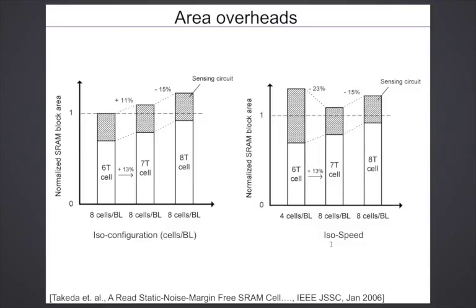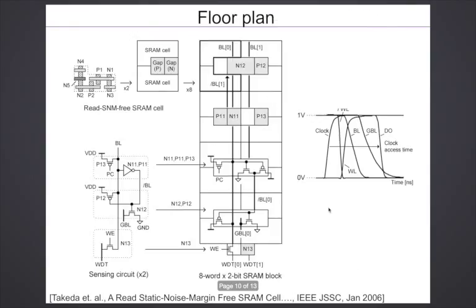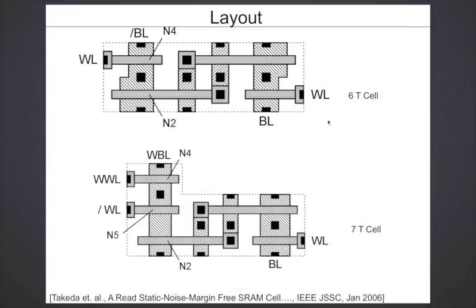What they are doing is giving them the same speed as that of the 7T and 8T. The 6T cell pull-down current seems to be lower than that for 7T and 8T, because the 6T access device is narrower compared to the 7T or the 8T. So the cell current also is lower for the 6T, so the speed is lower.